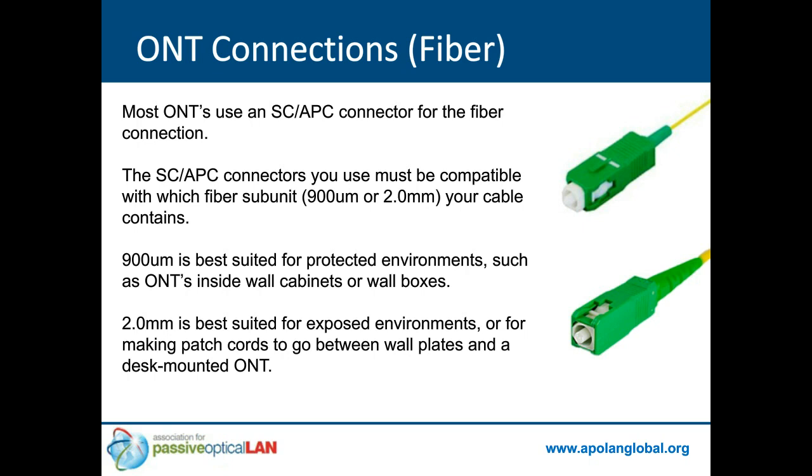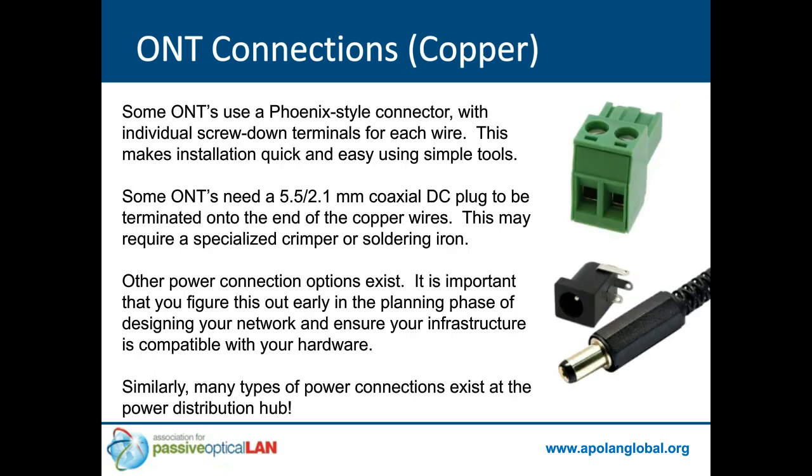We also need to think about the copper connection to the ONT. And this is going to vary by ONT manufacturer, but I've put here some common techniques. One style is the Phoenix style connector, which is that green block. The nice thing about these connectors is they don't require specialized tooling. They just require a screwdriver to terminate.